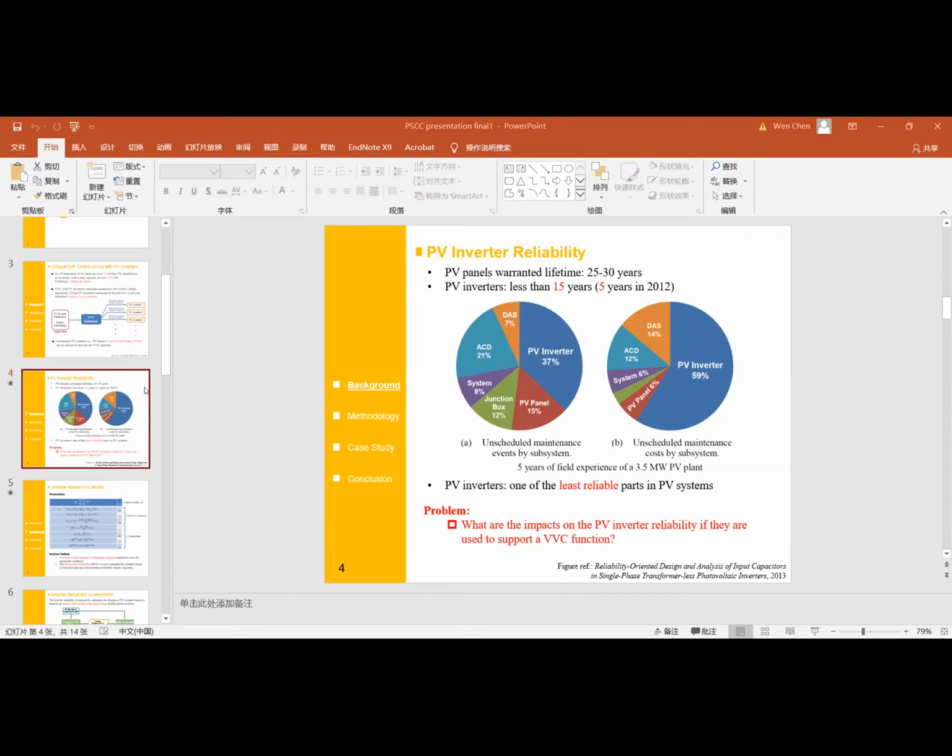Affecting positively. So do you mean the location? Whether the location affects it? Yes, I think so. I think the location is very important because for different locations, there will be different reactive power output results. This VBC model has a very important input data, that is the system parameter, including resistance of the lines and also the bus load, and this could really affect the reactive power output of the inverter.